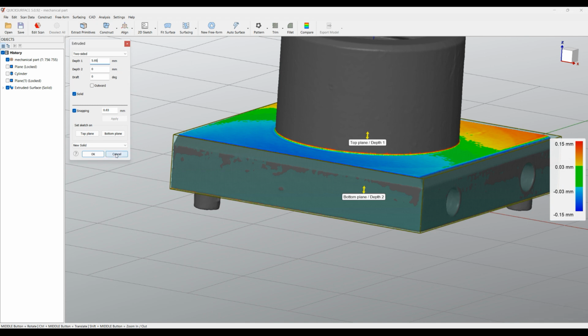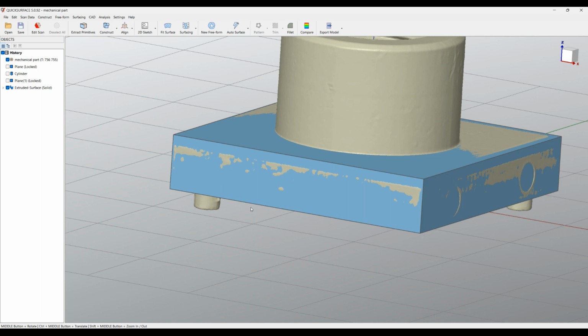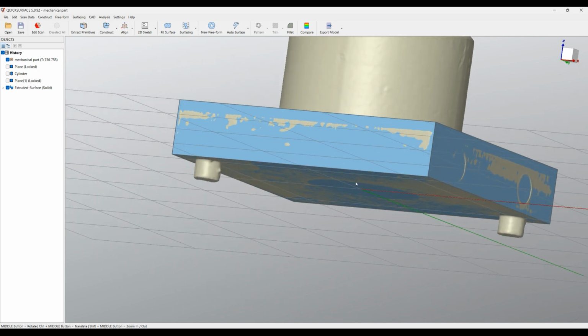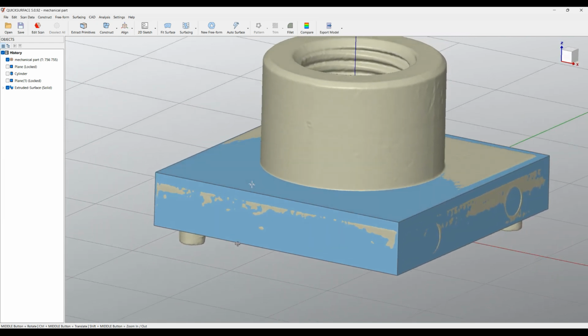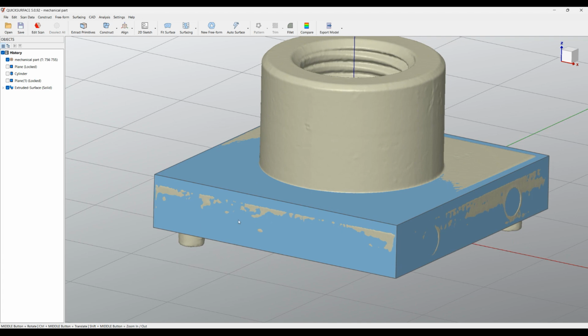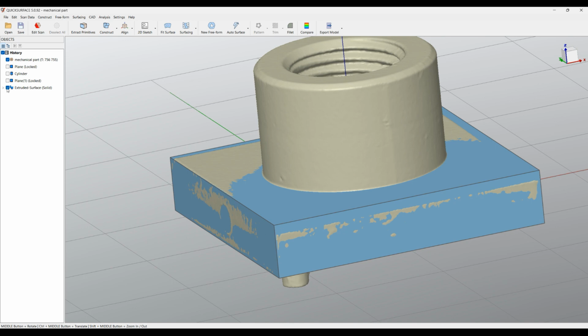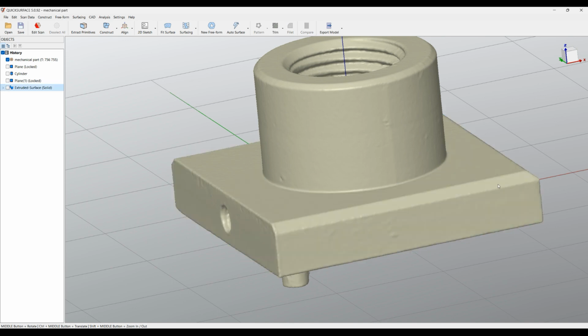Now I assume that I'm happy with the result and press OK. Because we started from the initial plane, there is no need to create a negative extrusion, so we are perfectly fine with the result so far. As a next step, we can create our chamfer. Let's hide the body for now so you can understand this is on the side.